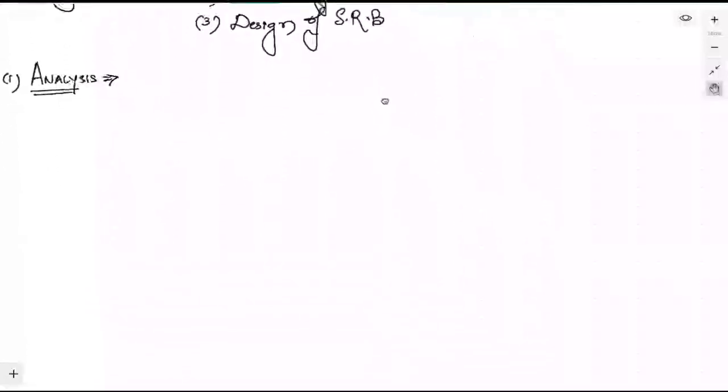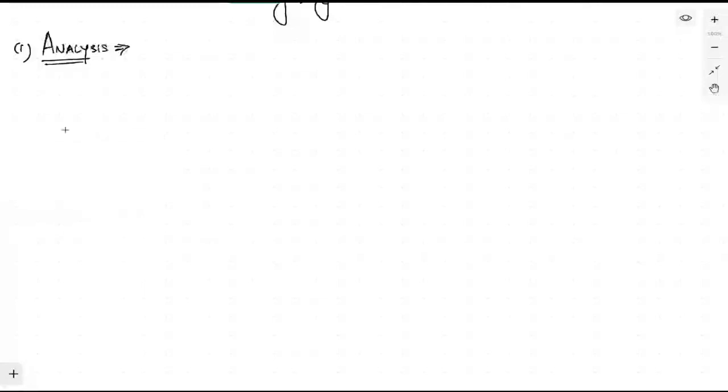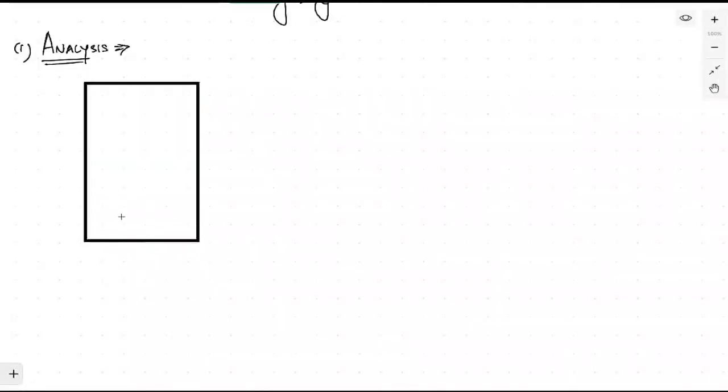Now, we are using the WSM method. WSM is also known as the elastic method. Now, what is the elastic method? The elastic method says that whenever the structure yields, you consider the structure to have failed. The structure will not reach its ultimate state. You have to consider the structure failed whenever it reaches its yield state.